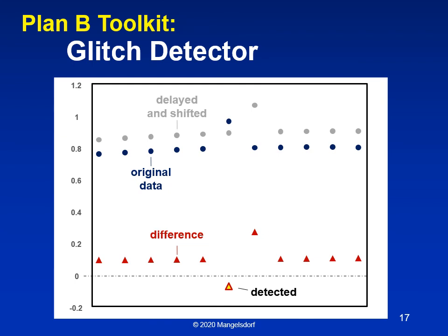This can be useful for real time, but it's almost essential for bit error rate testing, because there's no way that you could test the billions and trillions of samples required to find, for example, low metastability errors and so forth. You can't do that any other way except in real time or almost real time with this decimated data. So this is, I think, a very useful thing to have on your silicon.